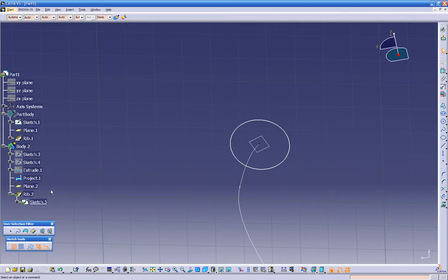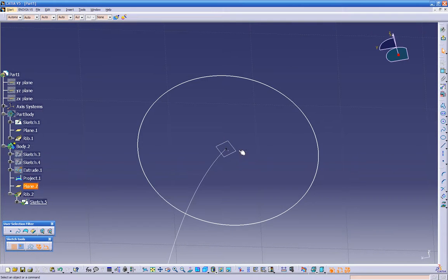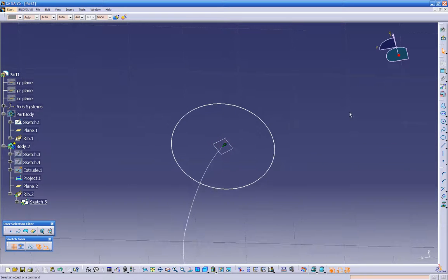Let's turn on our project. So we gotta make sure we move this arc on the center of our projection curve. So let's pre-select those two points, the point of the curve and the point of this arc. Right click, before you click it, click coincidence. Now we got our arc in the center.